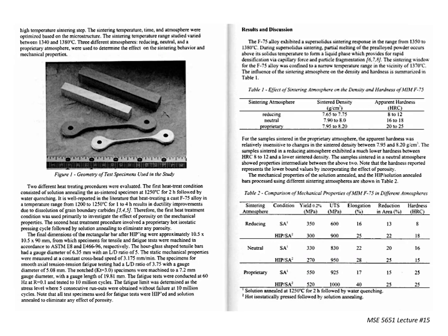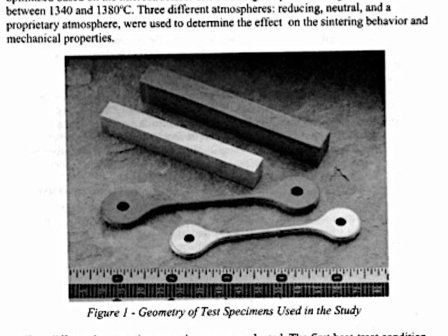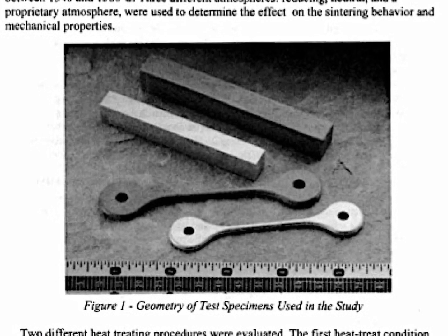We go into a picture of this. Did I miss? And that's shown here in this image. So it is what you expect it to be. And actually, again, we're talking about doing this in the lab, setting up a lab to do this, where you have the injection molded one, and then you have the sintered one. And the injection molded one looks exactly like the sintered one, except the sintered one is smaller because you've removed the binder, which made it shrink, and then you've sintered it, which also made it shrink. All right, but this is the goal.